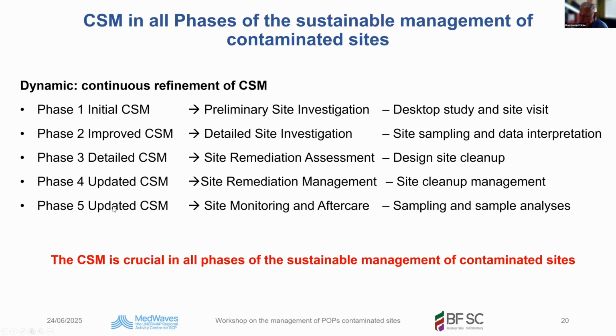And as I said earlier, after remediation, you may have remaining risks, so remaining contaminants, and therefore you enter into your last phase, the phase of monitoring and aftercare. You sample and you take note of what has changed on site due to pump and treat, due to natural attenuation, and then the situation changed, so you update your conceptual site model. The conceptual site model is crucial in all phases of the sustainable management of contaminated sites. It's important. This is the most important tool to manage contaminated sites.